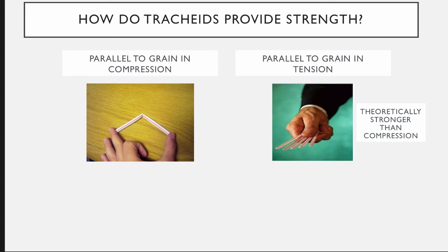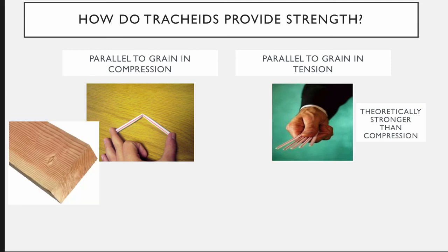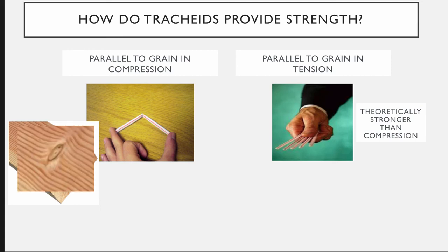But wood is an organic material. And in fact, in our sample that we looked at, there was actually a knot. And if we look closer at that knot, we can actually see that our grains are discontinuous around the knot. Some of them completely stop, and you could pop that knot out. Some of you may have looked through peepholes in fences where there had been knots in the fence board and they've just been popped out. They are a discontinuous, brittle material.